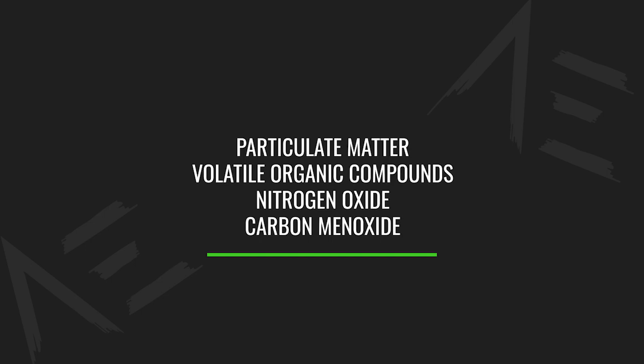But to answer the question I've been trying to answer with all of this, yes, ozone is a very important outdoor air pollutant, but it's a maybe for my project, or more accurately, it's a not right now. My reasoning being ozone is formed from NOx and VOC. And since I'm already monitoring these two air pollutants, I figured ozone can at least be implied. Keep in mind that my decisions are also influenced by cost, as these very specific sensors can get very expensive. So the mobile air quality logger as of right now will monitor particulate matter, volatile organic compounds, nitrogen oxides, and carbon monoxide. And I think that's a good combination for a start.